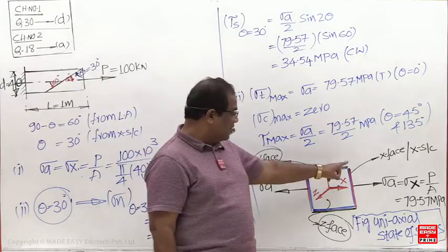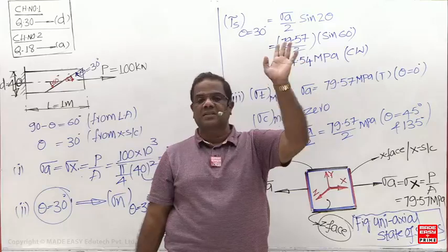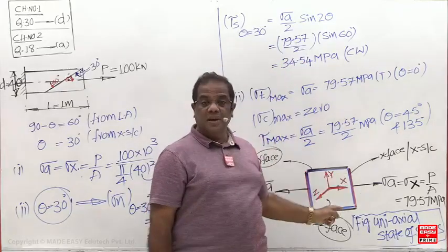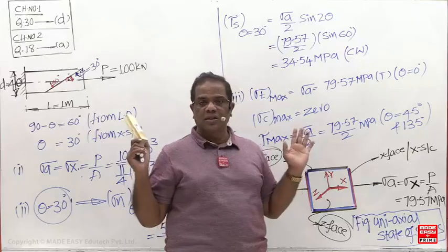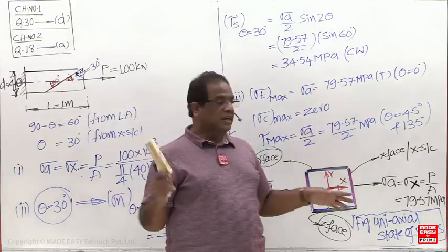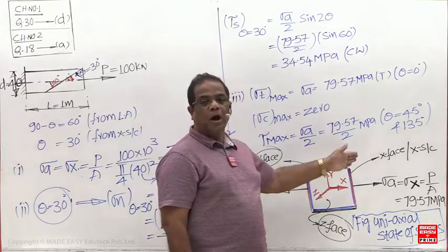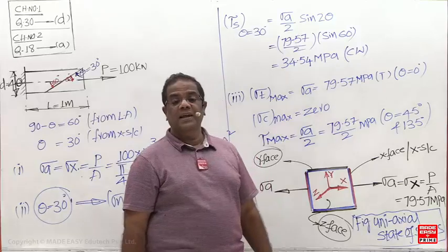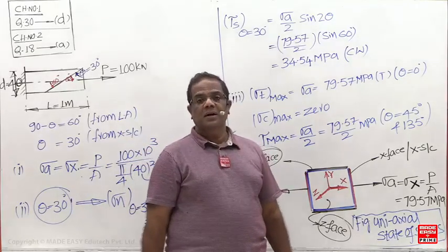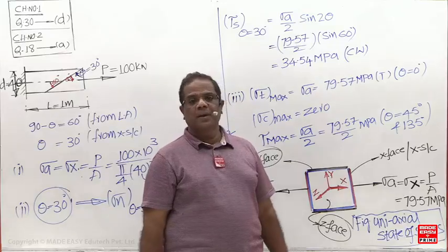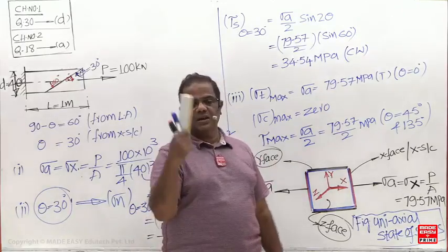So remember, these figures are giving stress only on 3 planes. On the 3 planes shear stress is 0, but on the remaining planes shear stress is not 0. For that only we are studying the oblique plane equation. What is the advantage of the equations of the oblique plane? With that we can find out the stress on every plane.